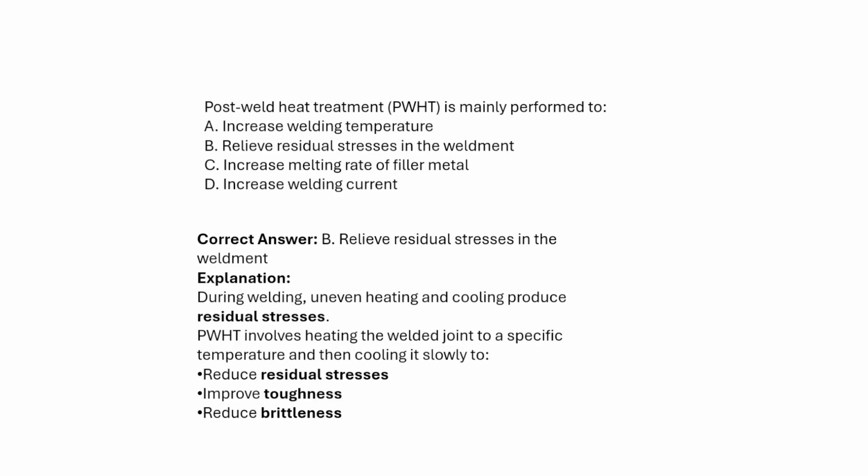Next, post-weld treatment is mainly performed to: increase the welding temperature, relieve the residual stresses in the weld bead, increase the melting rate of the filler material, or increase the welding current. So except B, all are giving reasons related to before welding, and those are other reasons. So the answer will be B, relieving the residual stresses in the weld bead.